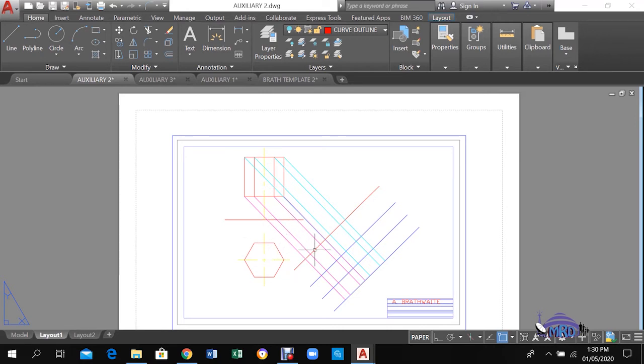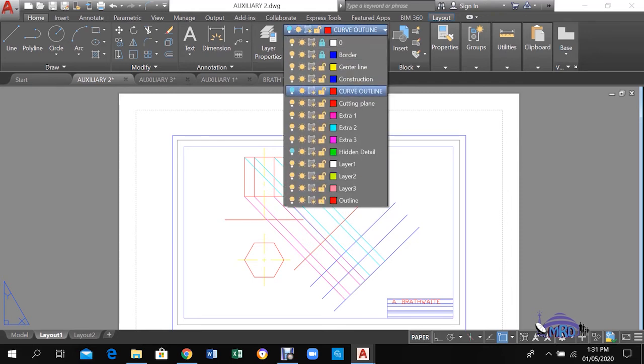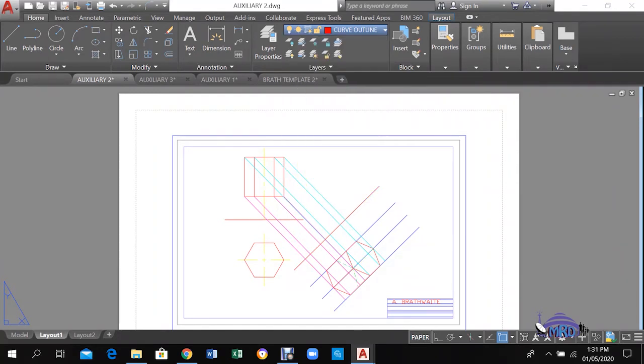So you'll be taking those measurements and marking them on the page. So since you can see two hexagons now, the top hexagon and the bottom hexagon being projected, if I look for the points of contact, you would see those points of contact being represented with the outline in this situation like this, and then you would see hidden detail being represented like this.